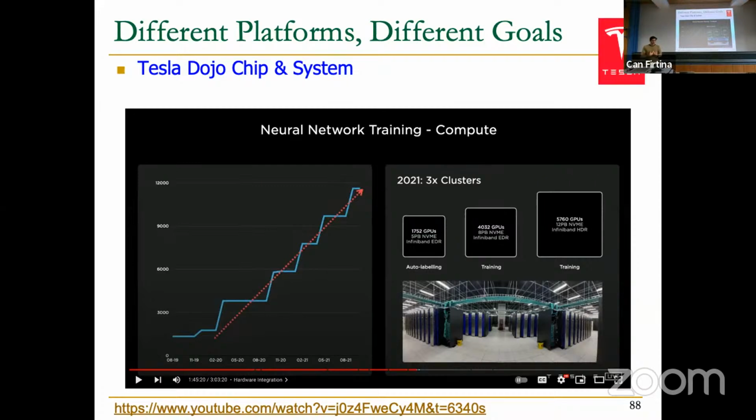So an architecture that is optimized for matrix multiplication doesn't need to be good at accessing data in an irregular manner. Why is that? Because in matrix multiplication, you either access a whole row or a whole column, so it's always contiguous data. The way that you access data in one case or in the other is completely different, and that requires you to optimize the architecture in a different way, up to the point that there might be some architectures that are not even capable of doing certain operations.